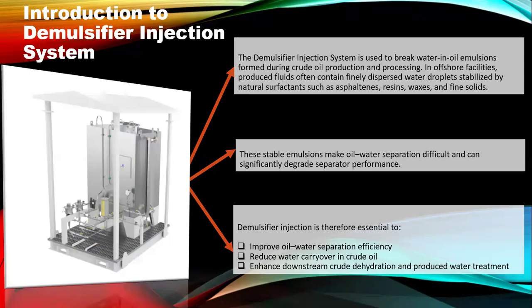While the crude oil, water, and other particles are coming up from the well, due to the pressure, they are mixing, and the water tends to blend with the oil. By the time it comes up for separation, it forms this emulsion that makes it difficult to separate oil and water, right? You can separate most of the water, but some part of the water is emulsified in the oil. In order to break that bond that was caused by high pressure and agitation inside the pipes, we need a demulsifier to actually do that.